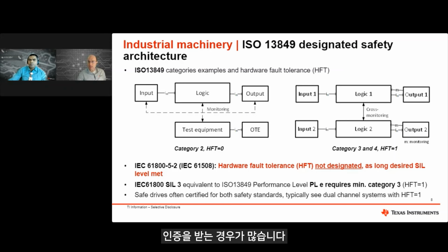Let's have a look at the subsystem of an STO dual-channel system. The table shows typical architecture to cut off power supply or PWM input to the gate driver. The architecture 1 on the left: Channel A, or channel 1, cuts off power from the anode of the 3 topside gate drivers. Channel B, or channel 2, cuts off power from the anode of the 3 bottom side gate drivers. This topology is, for example, shown as an example in the variable speed drive functional safety standard in Annex B. It also typically only requires 5 volt or 3.3 volt load switches.